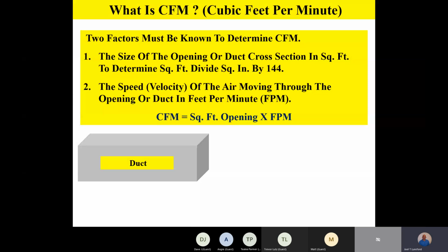Look at the top of the duct calculator in this example. We have friction loss at the very top, and that friction loss is going to be given at any given CFM. So in our example, let's say we're looking at 500 CFM. So let's just kind of walk through this. The first thing we talked about was velocity and CFM. So let's say we line that up.